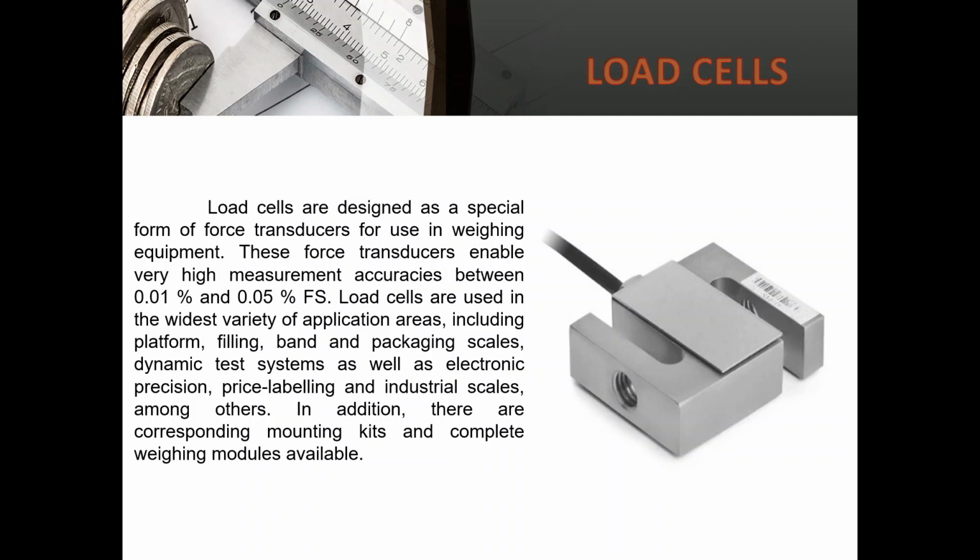Load cells are designed as a special form of force sensor. For use in weighing equipment, this force sensor enables very high measurement accuracies between 0.01% and 0.05% FS. The calibration of load cells is made in grams, kilograms, or tons, not in newton.